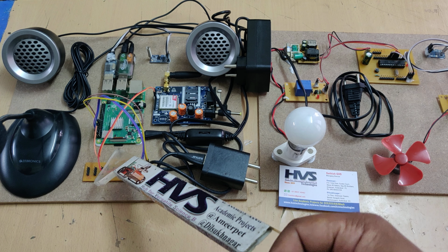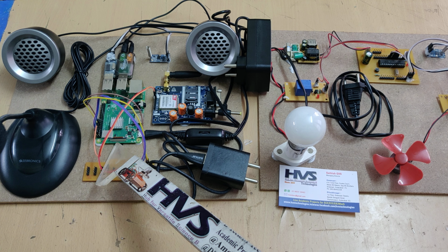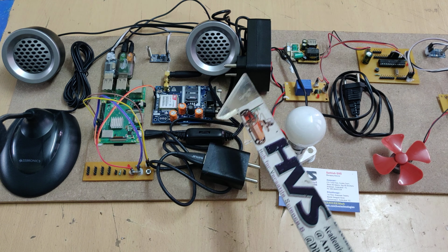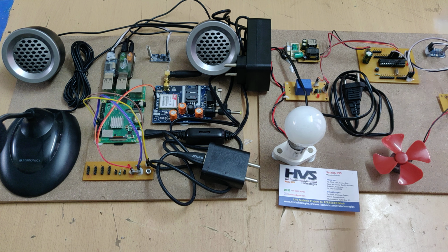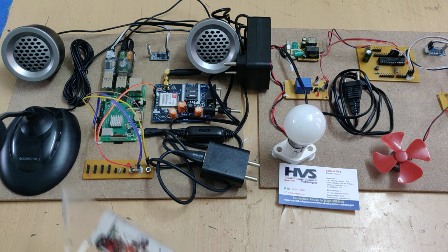The process is like initially we will format the memory card, then we'll load the Buster Raspbian OS inside that, and then after we need to install the modules. First module is like text to speech to announce the responses, and next speech to text to control the home automation, and also to announce the time, and also to send the message alerts whenever we say help.